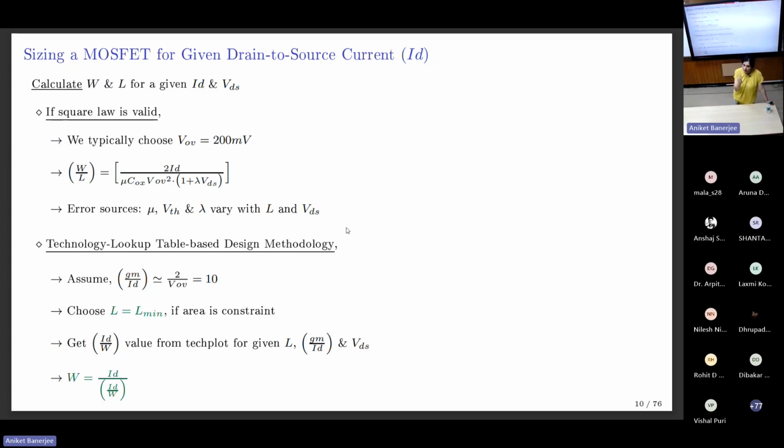So it takes time for us to build that: the lesser the overdrive voltage, the lesser the current; higher the overdrive voltage, higher the current. Or gain would become higher if I have higher length. It stays the same, because now you are just having gm*ro versus gm/Id. So the only shift you need is overdrive voltage to gm/Id. That's the biggest shift. Once that happens, the framework stays the same, because instead of overdrive voltage, my knob becomes gm/Id. It's all the same, but I would say it's better than an equation because you're looking at the plot, you're looking at the trends instead of just an equation.